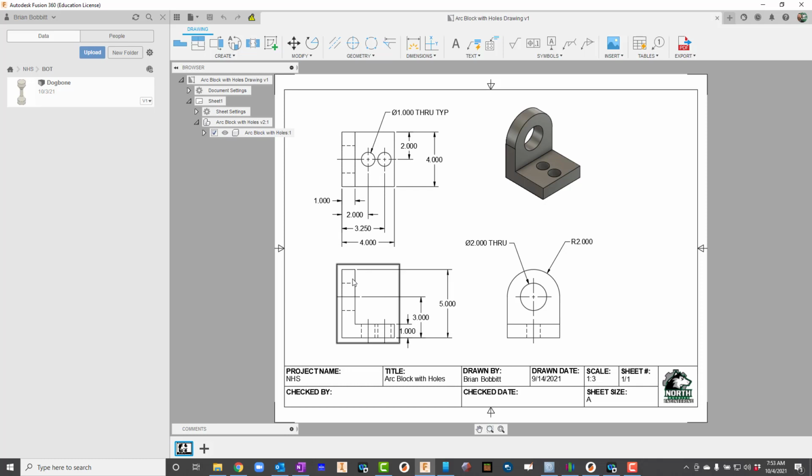Over here in the bottom left, this is always known as the front view. Then we move to the top view. And then over here we have the right side view. So basically we took this and we turned it so that we're looking at it this way. We took this and we flipped it up, so now we're looking down like we're a bird flying over the object.